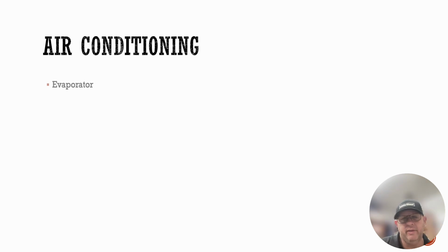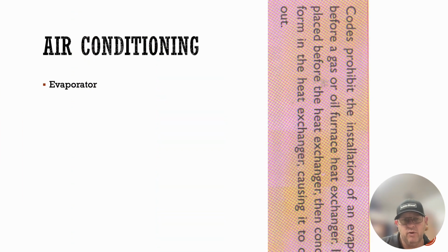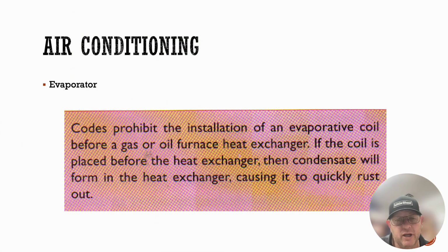So when we are actually dealing with the evaporators themselves, there is one rule of thumb that we must follow for these evaporators. Code specifically prohibits an evaporator on a gas furnace, LP furnace, or oil furnace from being set on the return side of that furnace.